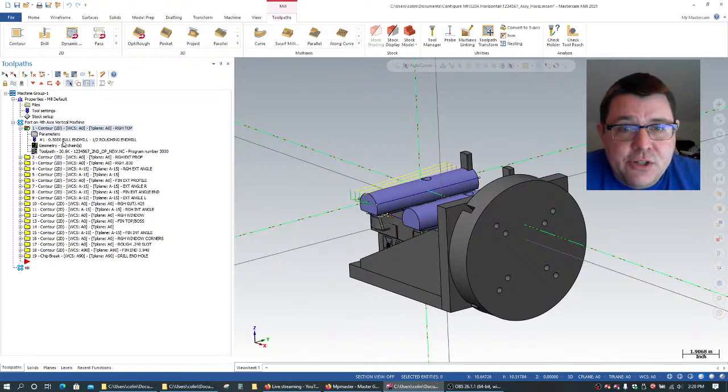And that operation itself has got some events that happen automatically in the post processor. So we have a header that comes up in the post. In the post header, basically, we're going to choose some output of some file strings, typically things like the file path, the file name, and then you're going to have things like potentially material list.